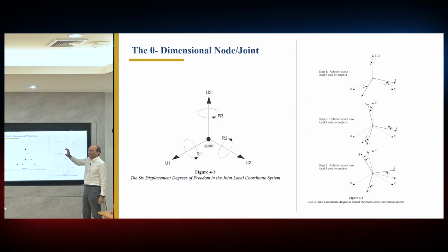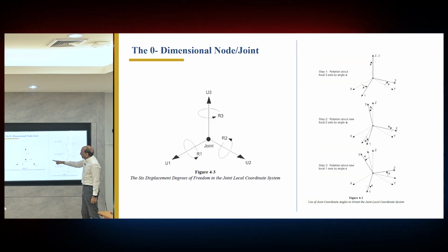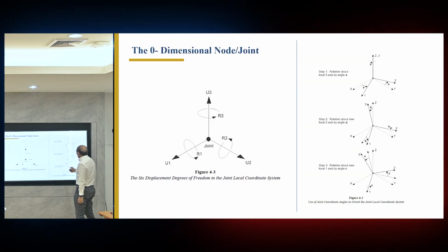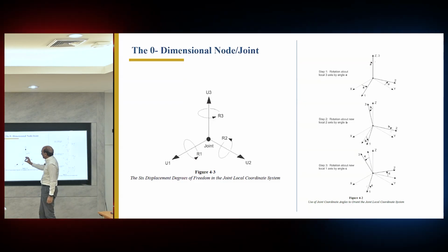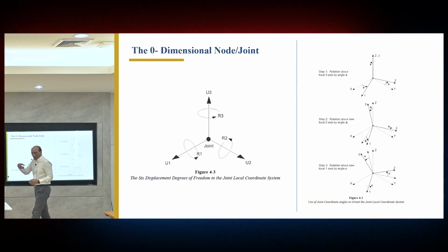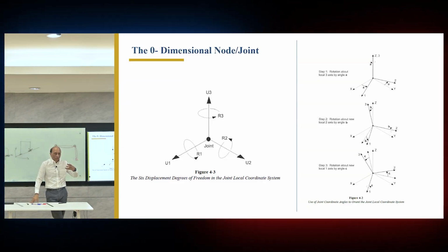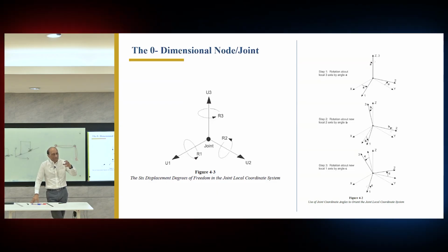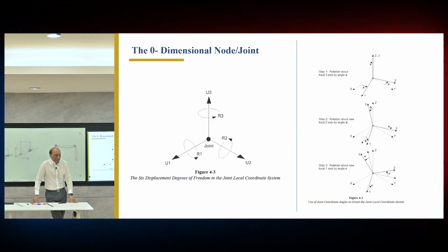The warping is at member level. It's not at the joint level. So then the problem is that this joint can be rotated in any direction. So there are 3 axes. So you can rotate it on this and then like this and then like this. So order of rotation becomes very important because depending upon whether you rotate about x first, then y and then z, or z first, then x and then y, you will end up with different configurations.